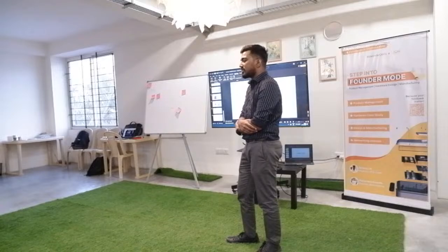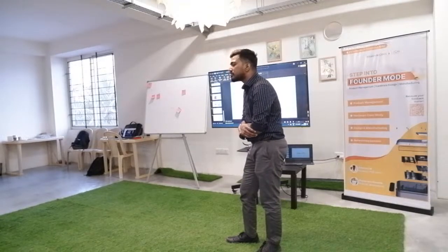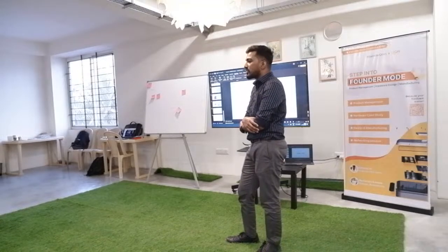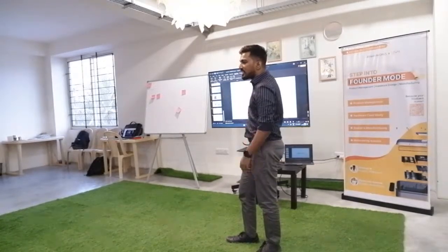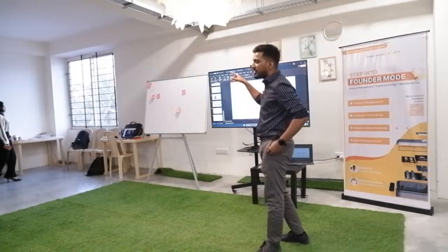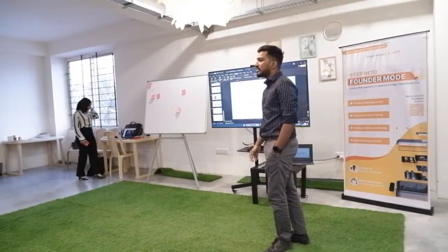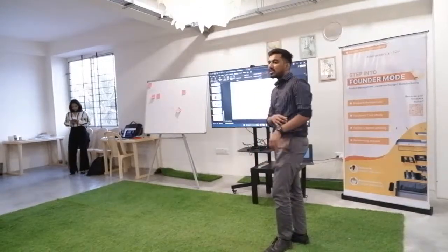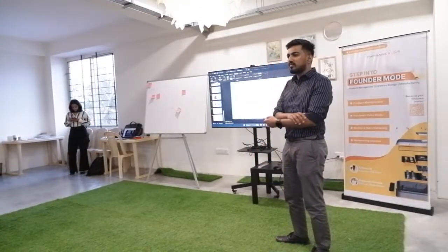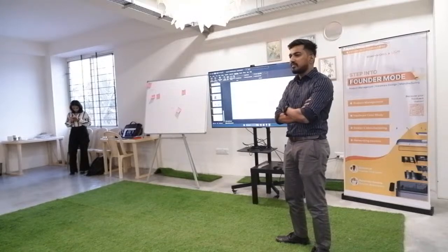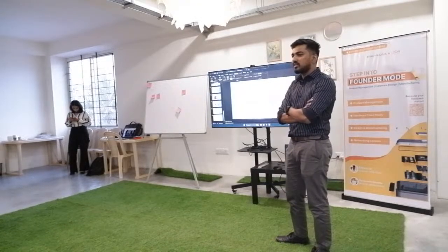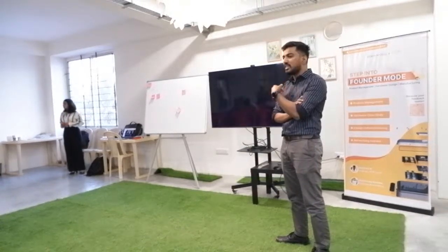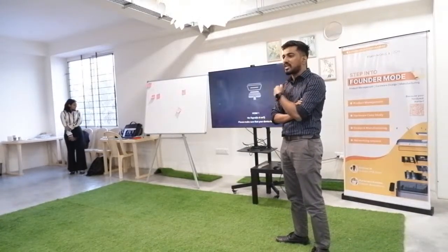My question is, I have to give one or two prototype boards also to assemble. Yeah, you can. So you're asking about the assembly platform, right? Yeah, there is an option where you can select between automated and manual assembly. So you can select whichever you want. There is no minimum order quantity. When we opt for manual assembly, they also ship the components together with the PCB. We can assemble at our workspace. Yeah, you can do that. So you can procure the components separately, get the PCB separately, and then just bring it to your place and assemble it.